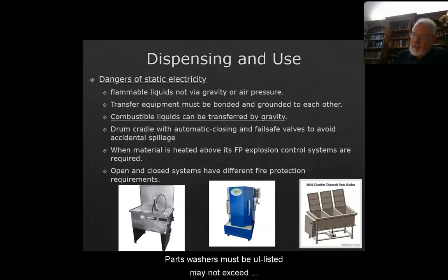Parts washers must be UL listed, may not exceed liquid limitation. Remote solvent reservoirs may not be used for soaking and should have flash fire control systems. Multiple machines require proper ventilation and separation. Machines that recycle solvents by distillation must have operation manuals available and require larger portable fire extinguishers, 40 BC or greater, located within 30 feet travel distance.